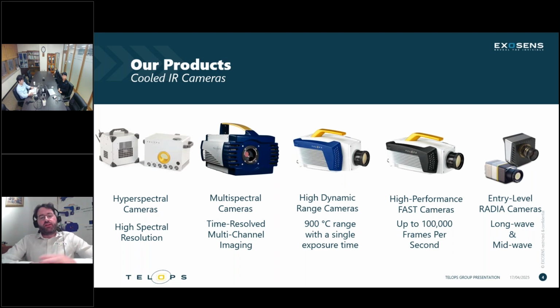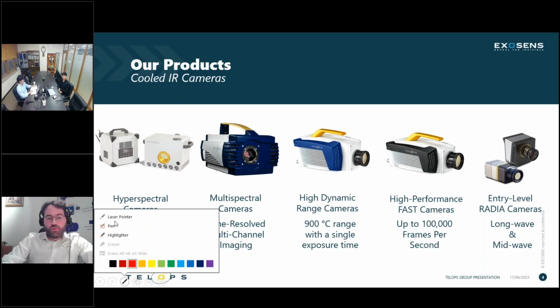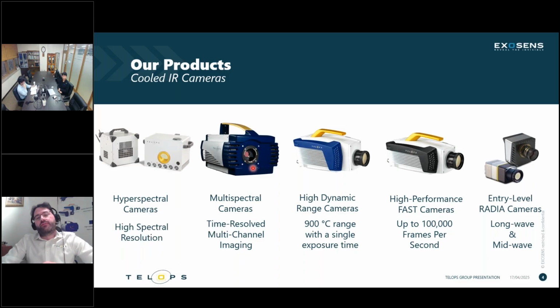In between a broadband and a hyperspectral camera, we have multispectral cameras where we have 8 filters rotating quite fast, so we can have a simultaneous acquisition with 8 different filters, either neutral density filters or spectral filters. So for faster acquisitions compared to hyperspectral systems, but a lower spectral resolution, then that's something that could be interesting.